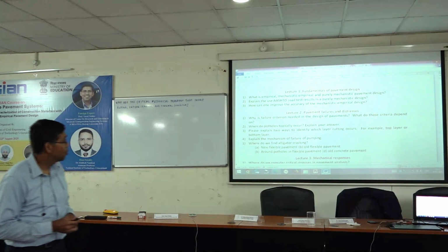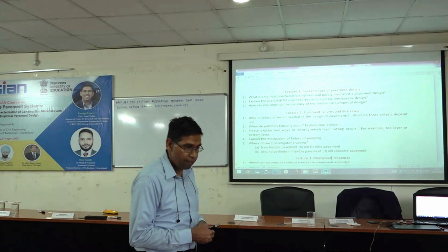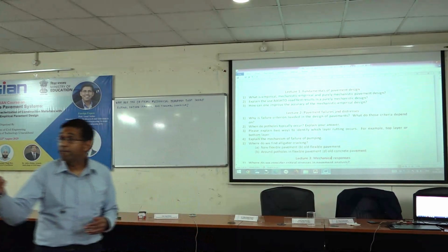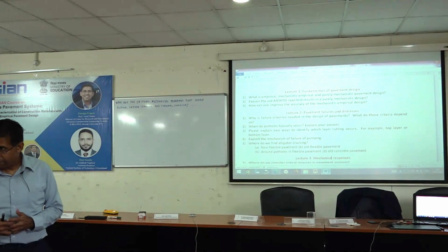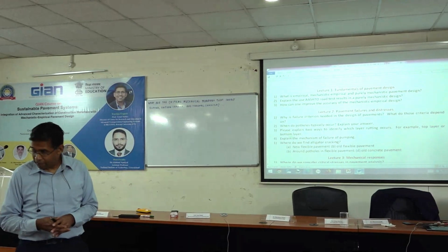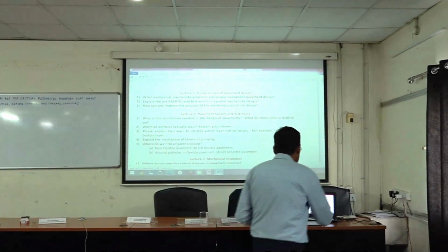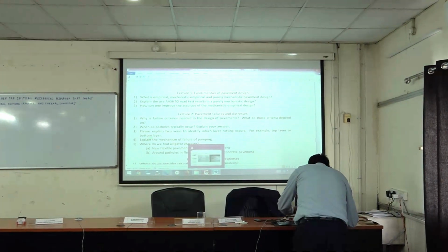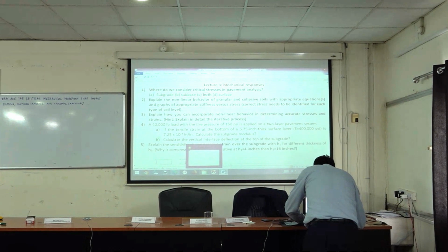They force the water and soil splitting. From the lines, water will penetrate into the slab, then with the traffic, the water will come up to the top. Correct. So you have failure of the joint. The joint loses its structural integrity, and then you have this happening.